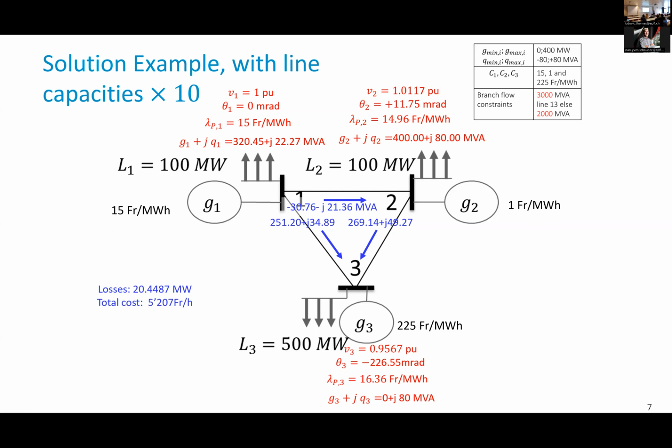This is why controlling electrical grids must be done again and again. It is to make sure that all those flows occur such that the voltages and the line currents are within acceptable values. And I mentioned that if I add a lot of solar panels, which means if I generate a lot here, like we're doing here, because now we're generating 400, that provokes an increase in the voltage here of this bus.